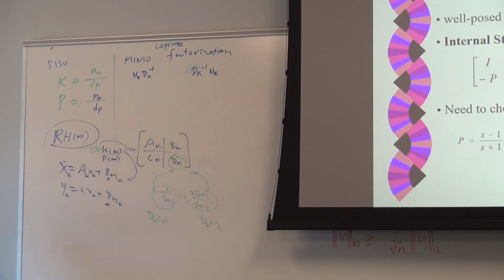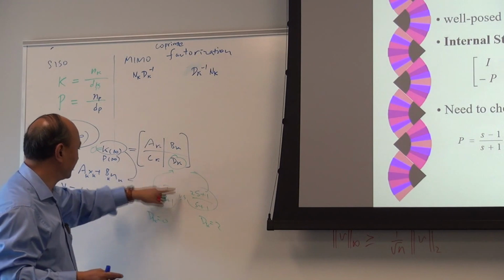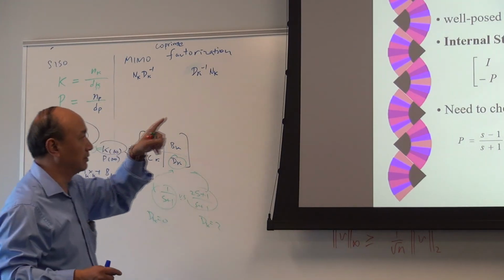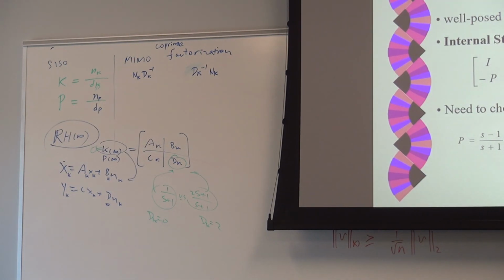So in summary, that's why we need to talk about RH infinity family. This is a big family of infinite members, about all the real, proper, stable transfer functions. All of them. Okay? So we limit our discussion on this. So in this case, then we don't need to worry about the well-posedness too much. And if the D is strictly proper, then it's automatically well-posed.